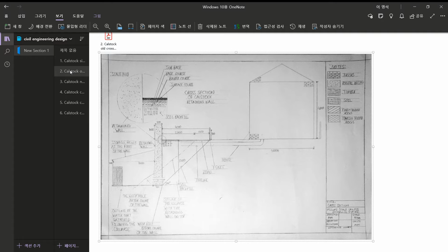The main issue we realized was that there was a large buildup of water in the soil which caused the wall to collapse. One of the possibilities of this was vegetation blocking the weep holes, which prevented water from leaving the soil. We deduced this from calculating the overturning moment of the soil and water together, which was 59.8 kilonewton meters, and the resisting moment of the wall, which was 32.2 kilonewton meters, which resulted in a factor of safety of 0.54. Therefore, the wall would have collapsed with the soil and the water together.